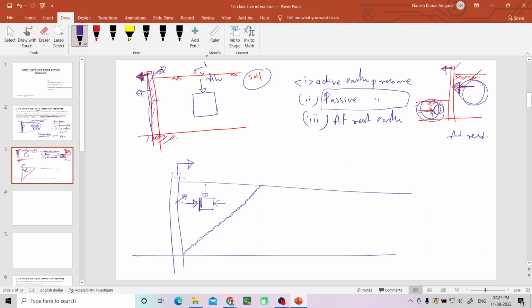So now to complete the equilibrium or plastic equilibrium state of the soil element, the soil element can be taken. I am magnifying it. There are all compressive forces. The vertical force is downward due to gravity, and due to the movement of the retaining wall, as it is passive, it is applying compression, right?